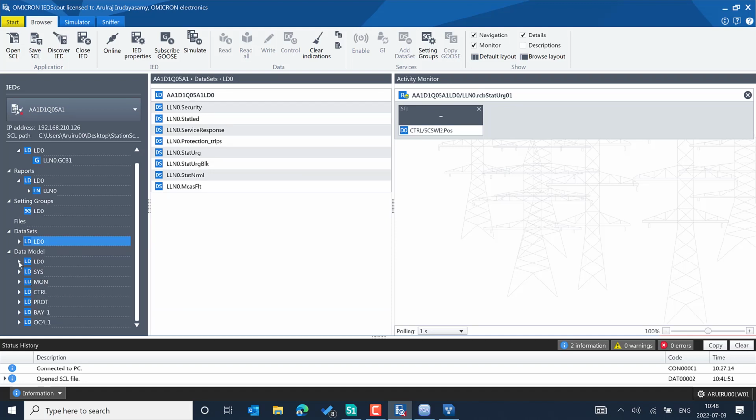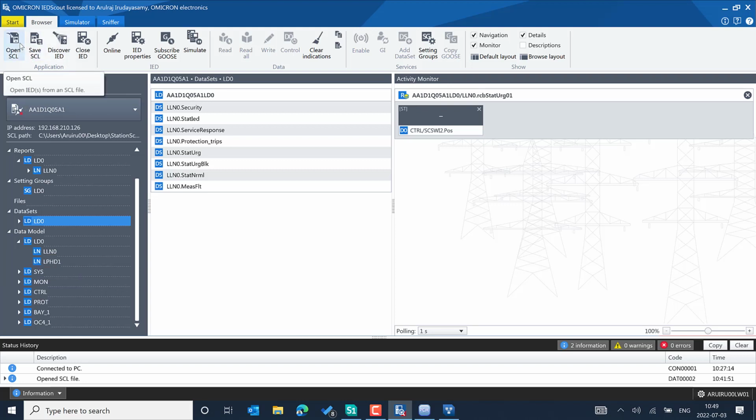So you are able to choose the logical node and understand its source based on the 61850-7-4, and the tooltip shows you the revision 2007, which is edition 2. You can also import the edition 1 IEDs, and you can see 2003 for edition 1 SCL file format.